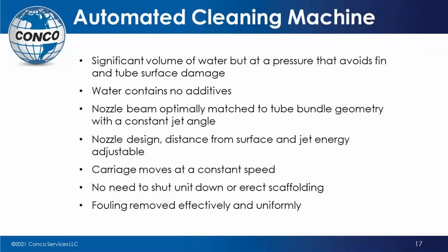You can also raise and lower the nozzles themselves to meet the dimensions of your particular unit. You get a consistent and solid pressure driving the fouling out between the fins and down in through the unit so that you get a complete cleaning. The carriage moves at a constant speed, so that means that the entire unit gets cleaned evenly.